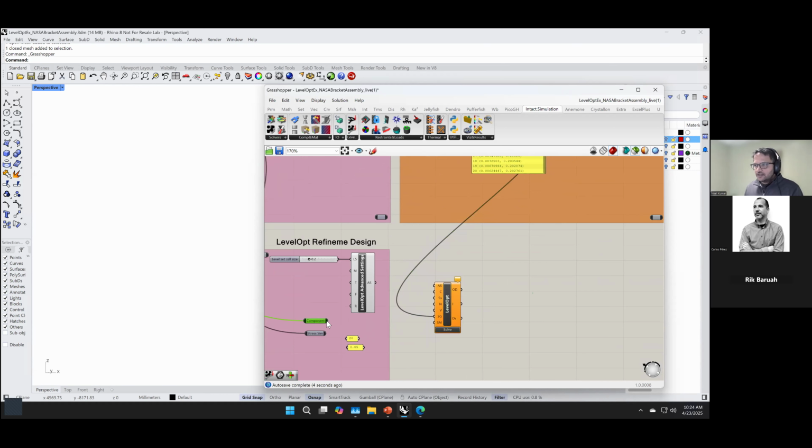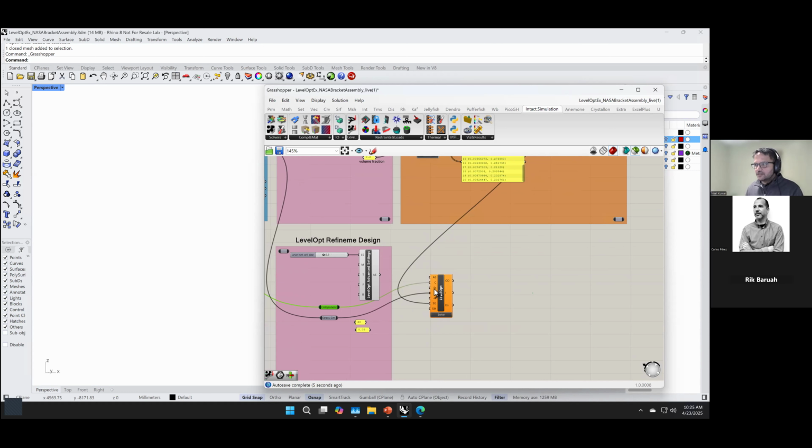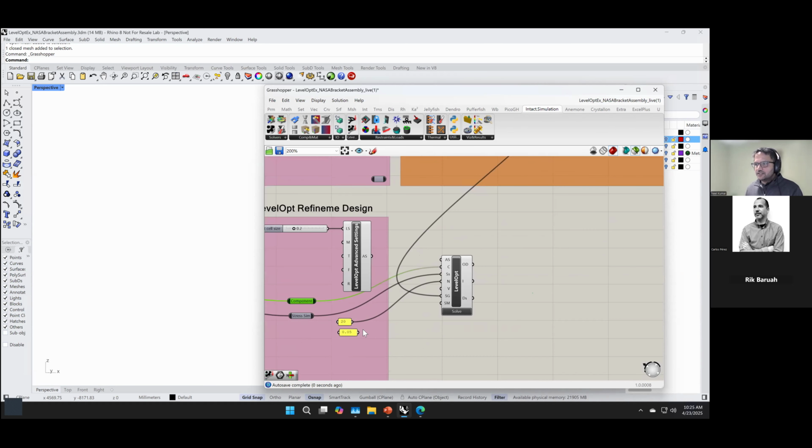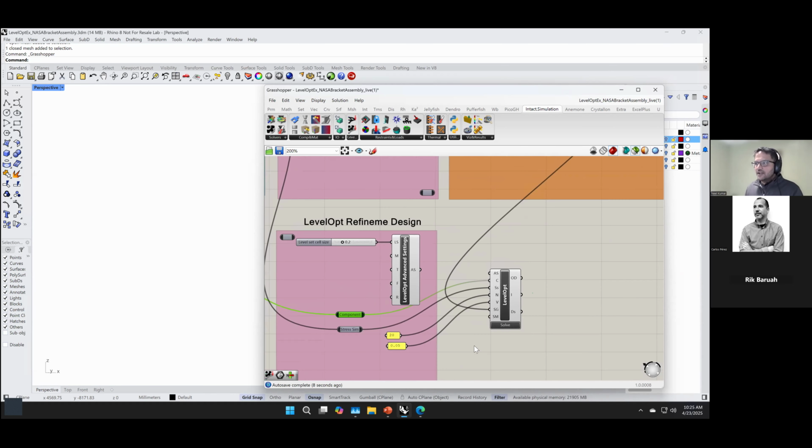Rest of the inputs look the same, so we want to optimize the same design domain. We have the same stress simulation. It's already here. I will still want 20 iterations, but this time I want to reduce the volume mass by almost 95%. So it'll go from 80% to 95% reduction. But I want finer features. So that's where some of these advanced settings come into play.